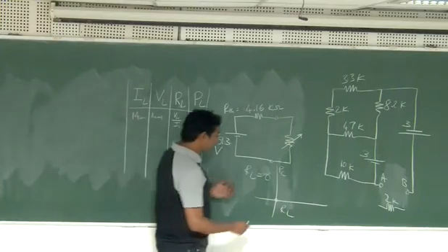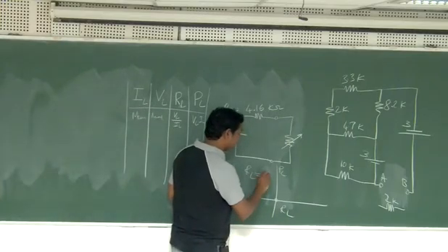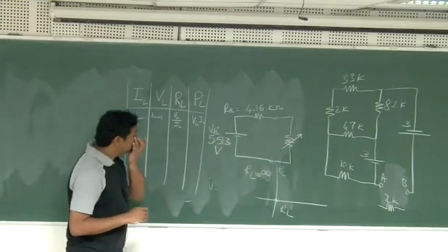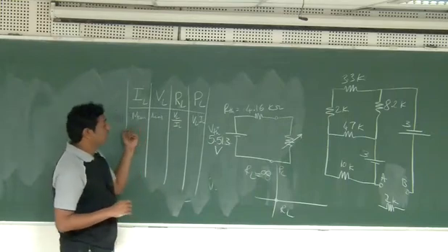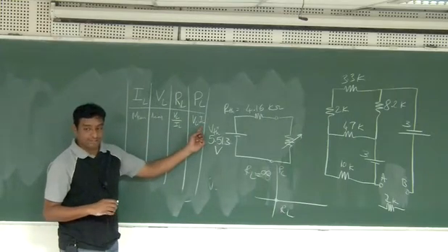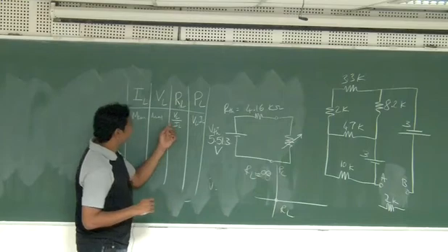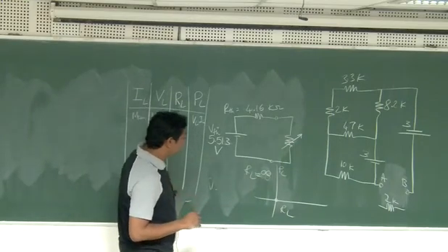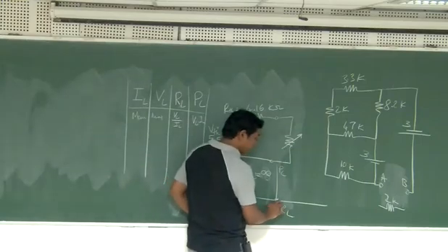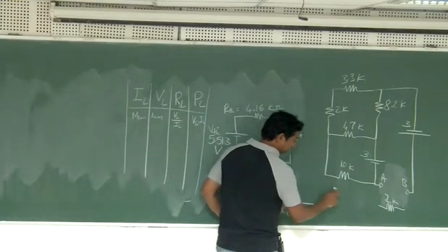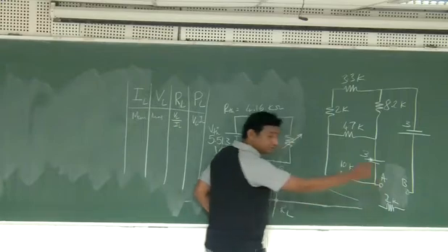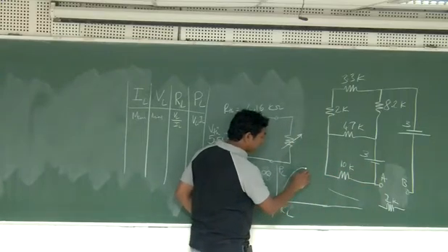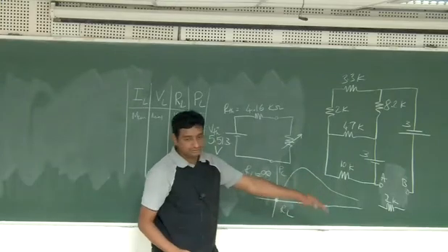Okay. And if I open circuit it, RL equal to infinity, open circuit, okay. Extreme case. In that case, what is I? I is 0, therefore P is also 0. And here RL is infinity because IL is 0. Denominator 0. So it will start from 0 and at infinity it will go to 0, something like this. Okay. It will touch 0. So in between it will reach some maximum value and then go to 0.